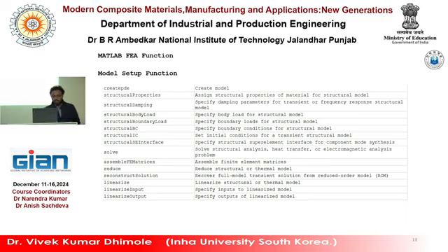Okay, and this is the setup function, please remember. This is the solution at nodal location, right; this gives a solution at the nodes. This is the function to interpolate, meaning we have the node solution and we want the solution inside the element, and extrapolate outside. This is the visualization function, pdeplot3D, pdemesh. So the command is for MATLAB. When you give this function command, it gives you the visualization in MATLAB only, not the GUI one, right.